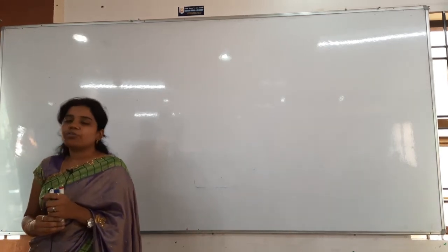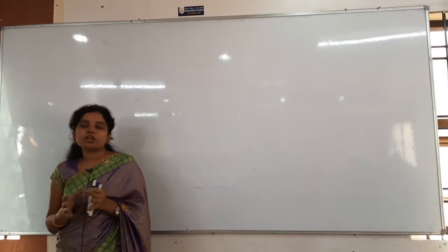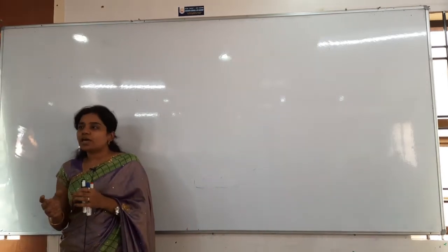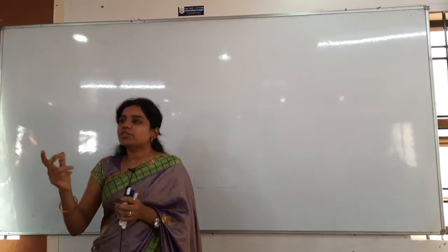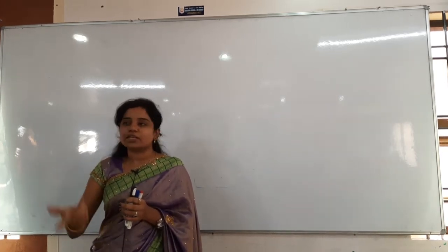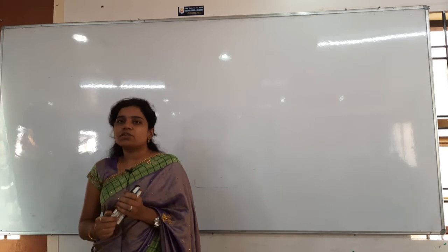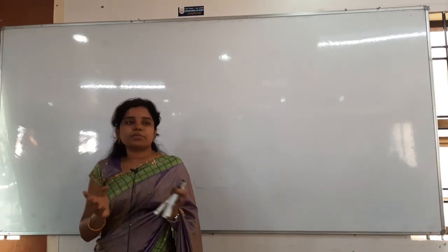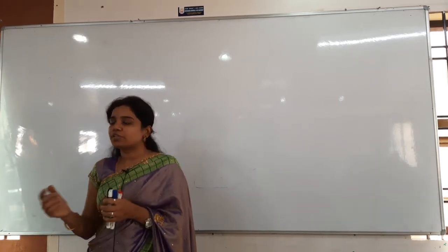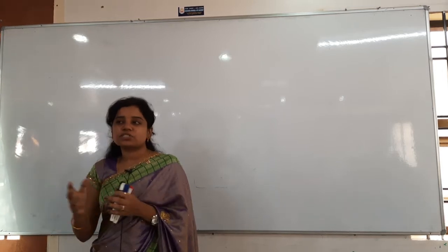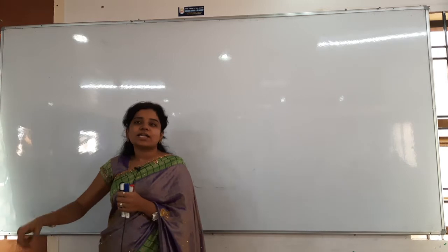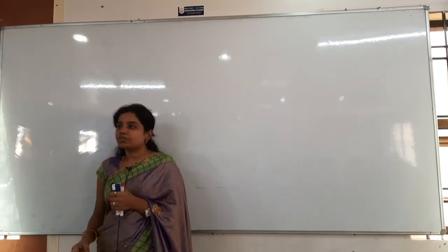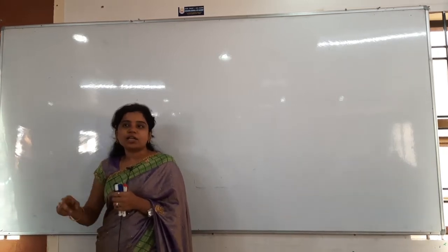But here the potentiometer will not depend on magnetism. In the magnetic effect, torque will be there. Due to the torque only the coil will be turning, and at that time you will get the current effect. You might remember that tau is directly proportional to theta, so tau is equal to c theta. Again theta is directly proportional to I, so torque is equal to NBIA.